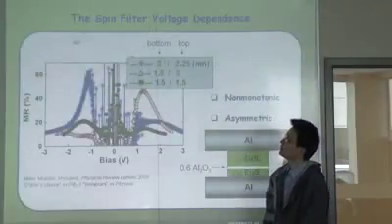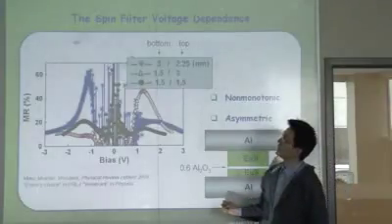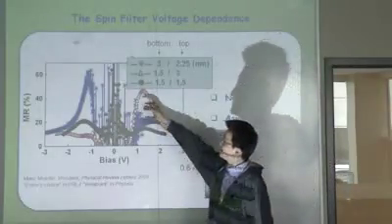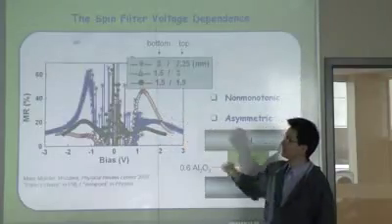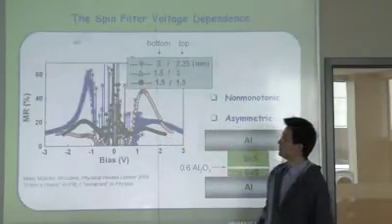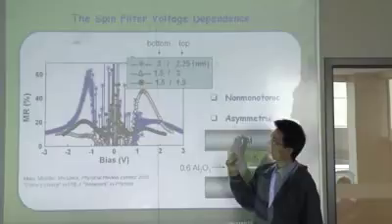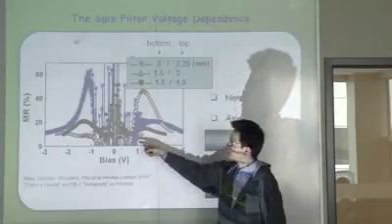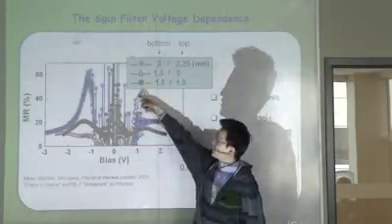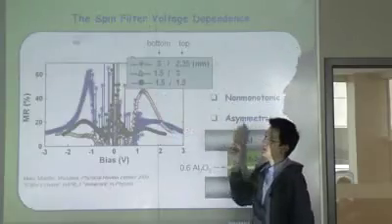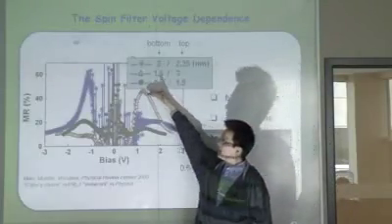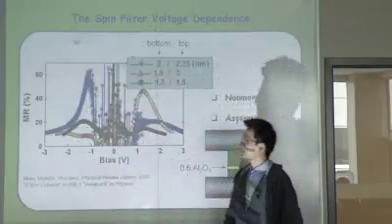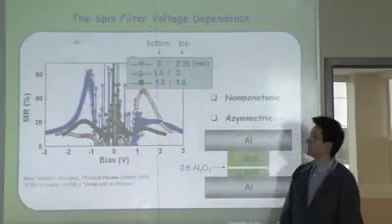Let's take a look at what happens with the spin filter magnetic tunnel junction. Please ignore the center part. This is pure noise because the device has a very high resistance. Two things you can notice right away. Firstly, the TMR behavior is non-monotonic. It goes up first before it starts decreasing. Secondly, it is asymmetric. On one side, the TMR is significantly higher than on the other side.